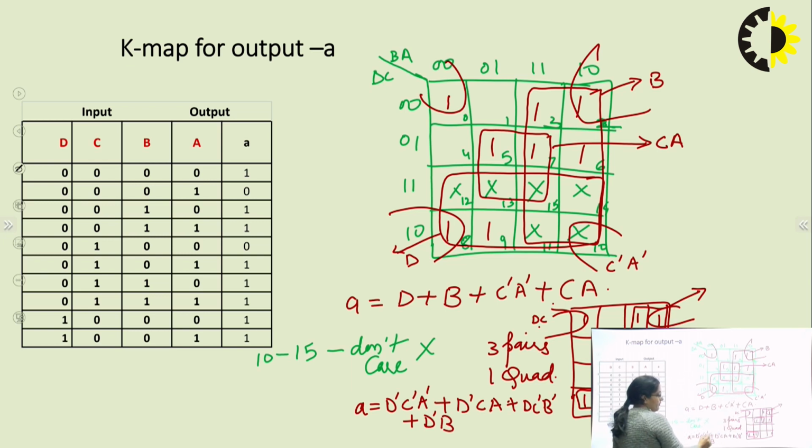So you can find that 3 terms are there, but it is having all the 3 input AND gates, and 1 is a 2 input AND gate. But here we will have a 2 input AND gate. So you can see that the number of literals is reduced if we go with the don't care condition. And here we have not considered a don't care condition. So to minimize, we have to cover all the expressions. We have to consider all the input combinations.